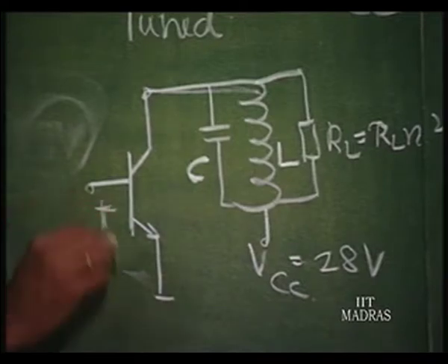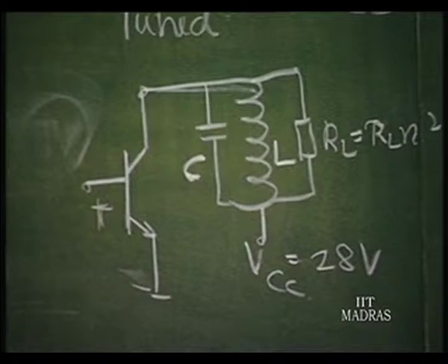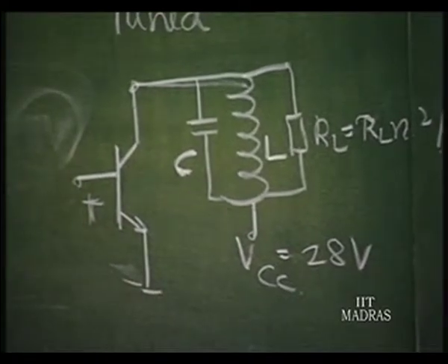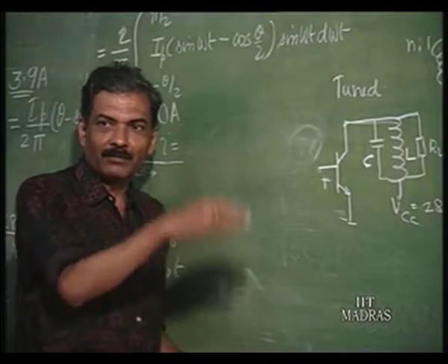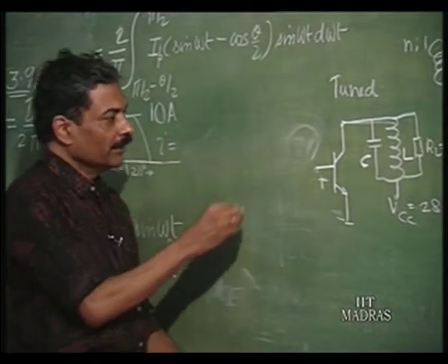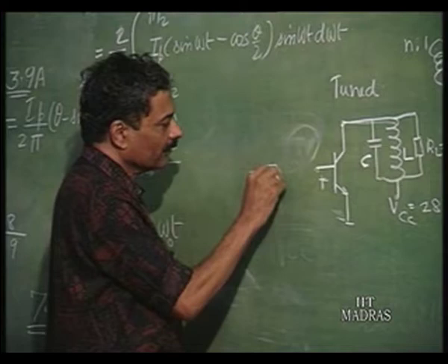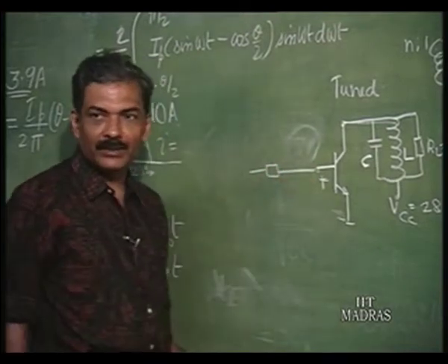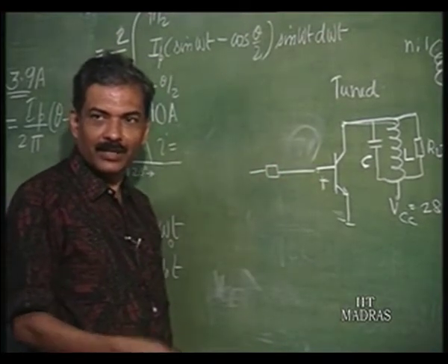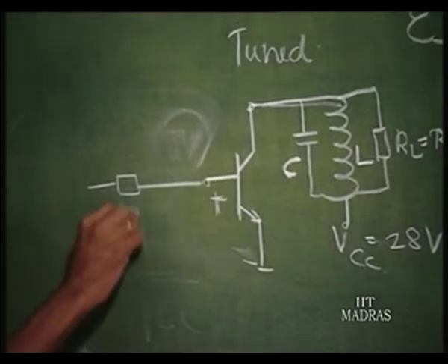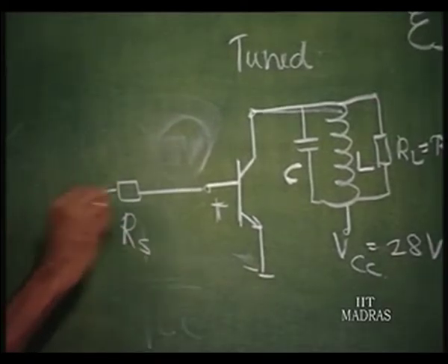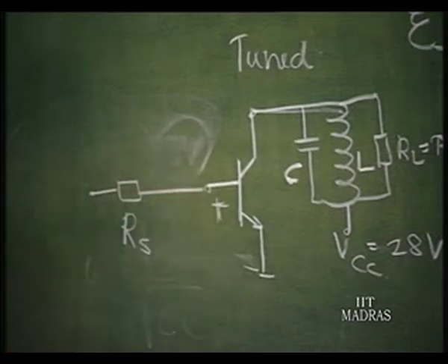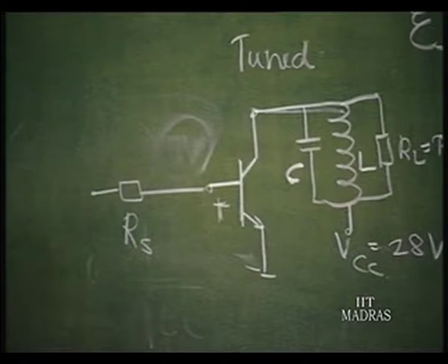Otherwise, in the case of a transistor, since it starts conducting only after the cut-in voltage is reached, that itself can be used for obtaining the waveform that you require. So, let us assume that we are not using additional voltages. We do not need all these variables. We will put a resistance here to restrict the maximum current as soon as it starts conducting, and we will assume it conducts only when 1 volt is reached. This is an assumption.